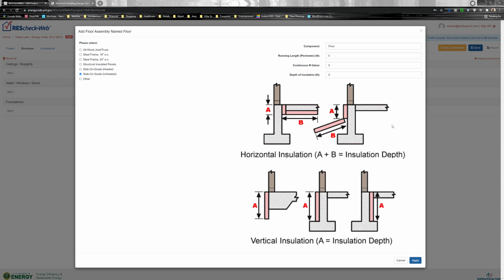And what I mean when I say they're pretty clear on, they're very clear that they want that foundation insulation to start at the top of the slab and provide in some way a thermal break, especially at the top, from allowing heat or cold, in our case, to radiate through your foundation wall or through your slab horizontally and then up into your space. The foundation insulation is supposed to be there to break that thermal bridge. It's especially important for the first foot, 6 inches to a foot.